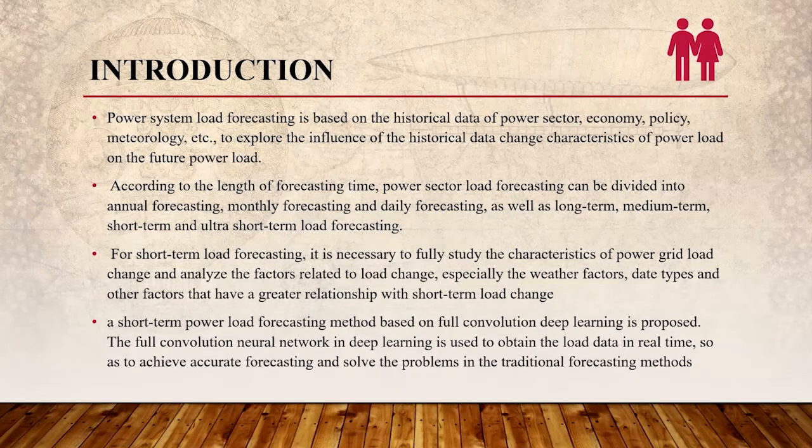The goal is to arrange daily and weekly power generation tasks for each power plant, including the determination of unit startup and shutdown, coordination of thermal power and hydropower, fuel procurement and supply, tie-line exchange power, economic distribution of power load, reservoir dispatching and equipment repair, etc. Ultra-short-term forecast refers to the forecast of 1 hour, 0.5 hour or even 10 minutes in the future, which is mainly used for safety monitoring, preventive control and emergency handling.